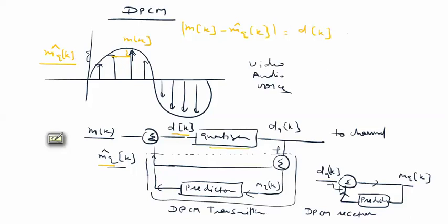After quantization, this DK is quantized, we call it DQK. This is the sample value, analog type. This is digital now. This DK is accumulating the previous value, and now it is the current value. The predictor predicts, the previous value is modified and the next cycle comes.